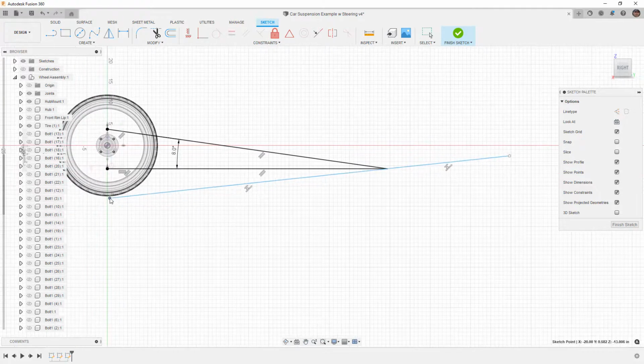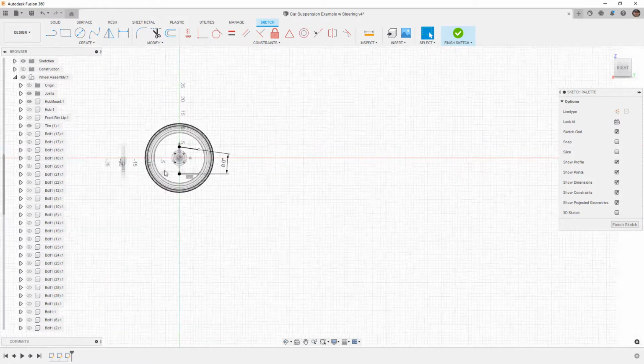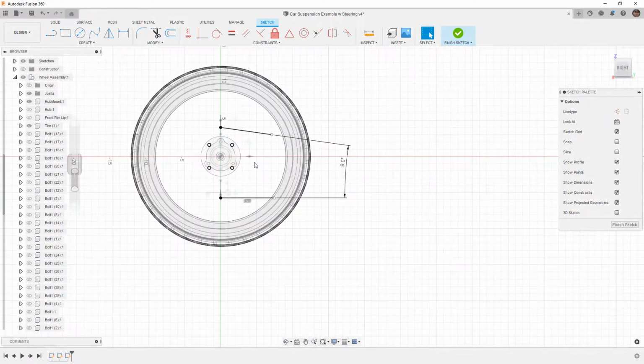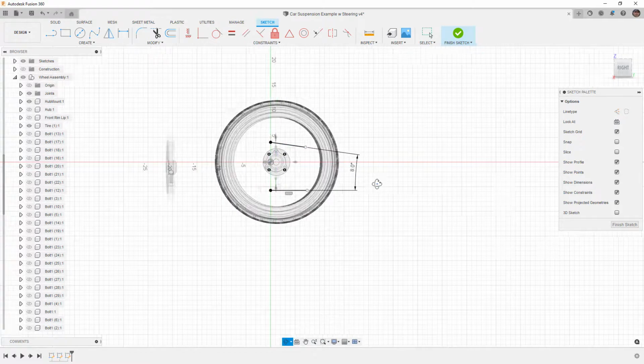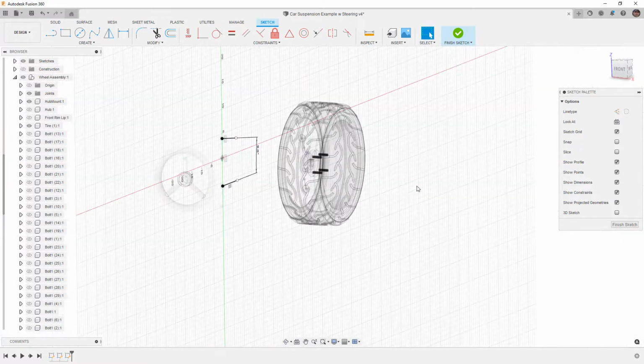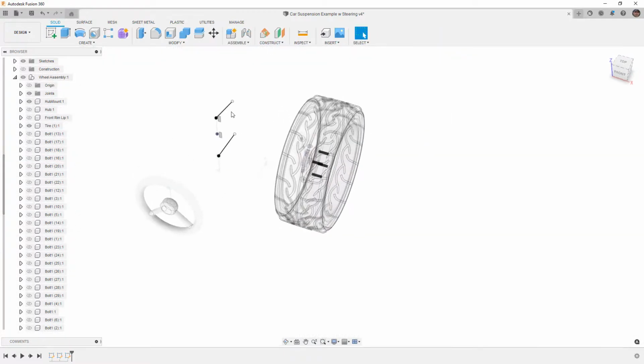So this would touch where the wheel or the tire touches the ground, and then we would sort of project these out. And this would help us better understand the location and the sort of moment that we're going to have on the center of gravity. And that's going to help us determine things like anti-squat, anti-lift, depending on if we're working on front or rear. But again, it's a bit outside of what we're talking about here. I just wanted to make sure we understood that these axes will project similar to how we did it in our 2-axis sketch.